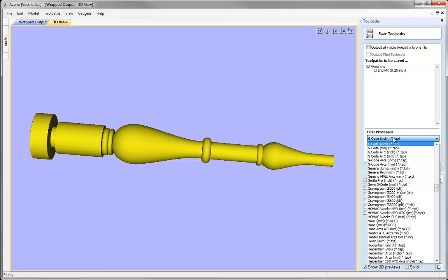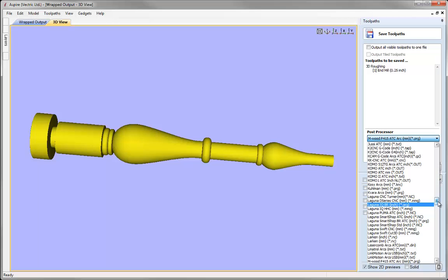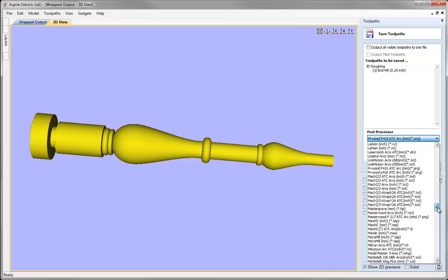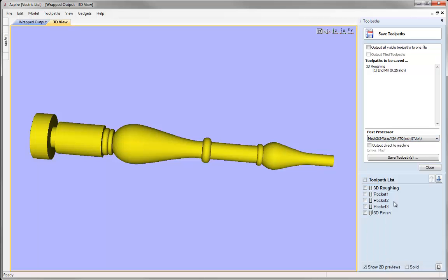If we have a look here, let's just hit M to search for posts beginning with M. We can see for the Mach 2/3 control program, we've got these special posts here, some set to wrap X to A and some that are set to wrap Y to A. In our case, we're wrapping the Y axis, so we'd actually choose something like that where we're wrapping the Y values to A, being a typical designator in G-code for a rotary move.